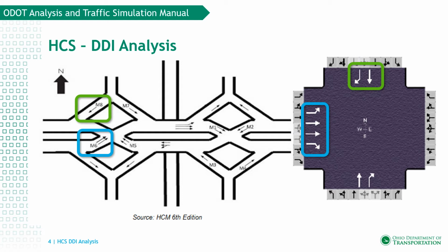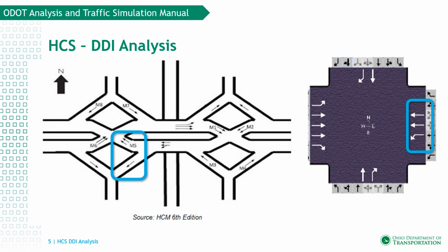Additionally, the eastbound right turn movement to the on-ramp should be marked as an unsignalized movement with a delay of 0. Because the westbound left turn onto the on-ramp is a free-flowing movement, it should be coded as an exclusive left turn lane and checked as an unsignalized movement. The delay should be entered as 0.